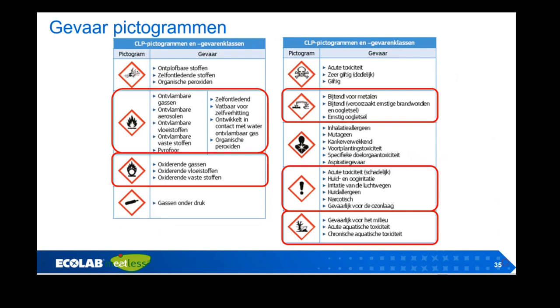It tells something about if there is a fire and you have an oxidizing product like peroxide, it will intensify the fire. So you also have to think about that. Also in storage, don't put an acid or an alkaline product together. So there has to be a minimum distance.